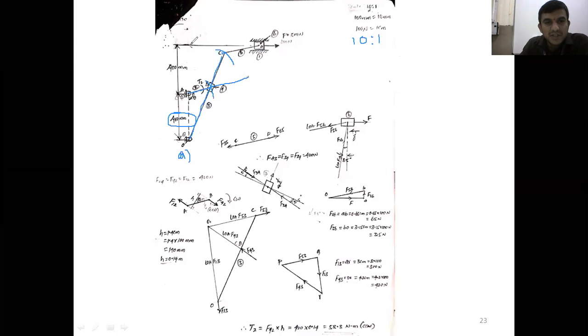400 mm, right? Means 40 mm reduced scale. From the 40 mm reduced scale, draw a horizontal line. Once you draw the horizontal line, now we'll get CD. CD is how much? 300 mm is given. Convert into reduced scale, that becomes 30 mm or 3 centimeter. Take the compass, 3 centimeter radius, C is the center, and draw an arc that touches the horizontal line, which is 400 mm, reduced scale 40 mm, vertical distance from the hinge. Now that point will be point D.